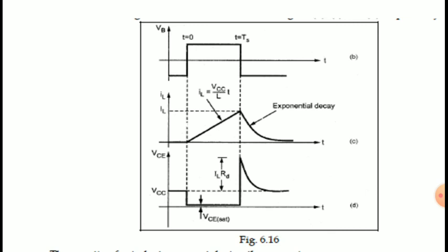That small portion of the entire circuit, composed of the inductor, resistor and diode, will get activated. The diode conducts, and the energy stored in this inductor will be dissipated through the RD resistors entirely, till it becomes zero. That is the exponential decay. The decay of this energy is exponential and it reaches zero.